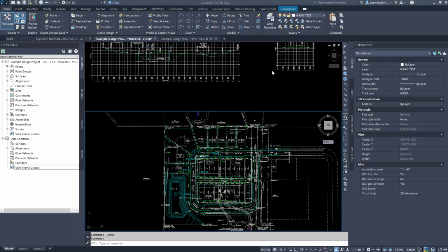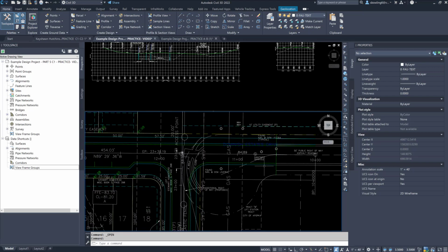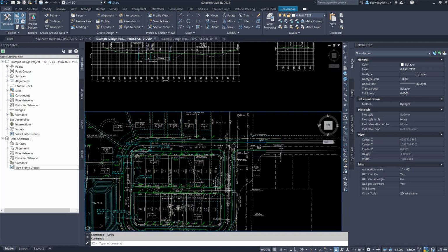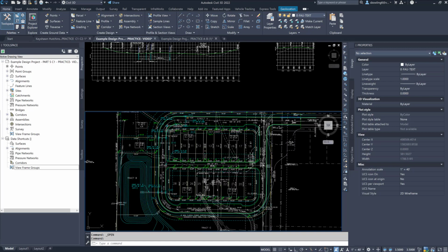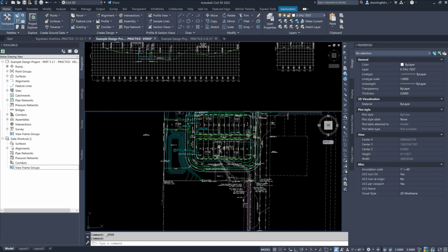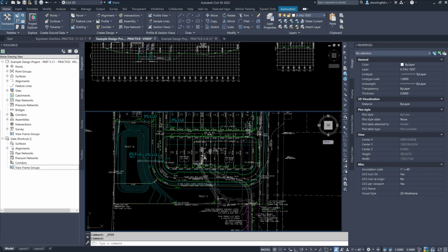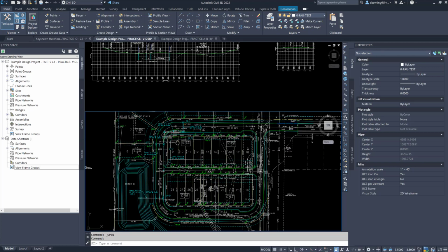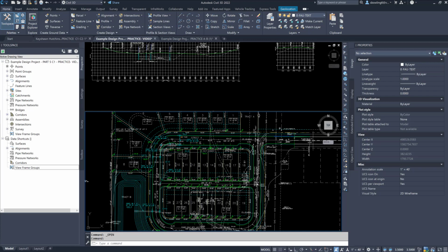In this video, I'm going to show you how to do a line of sanitary sewer. So basically what we're going to do is we need to take our sewer and tie it into this manhole. So what I'm going to start with is I'm going to assume that from this point right here, the sewer line is going to come up and connect to this manhole here. To do that, it's the same as creating storm pipes. And then a second run is going to start here and go this direction.